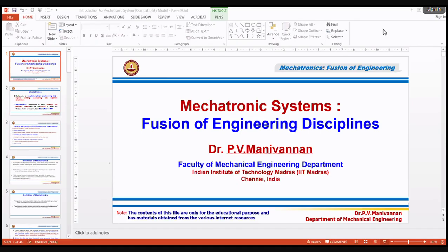Instead of aluminum, because of the dimension, for example, length is 10 centimeter, diameter 1 centimeter, correct? You made it, for example, in aluminum, correct? When you test, it shears because the load is more. Then what do you do? There are two options. You can increase the diameter. If you want the same aluminum material, you will increase the diameter of the bolt, correct? Raw material: instead of 1 centimeter diameter, you take 15 centimeter diameter, make the bolt, correct? Then again do the testing.